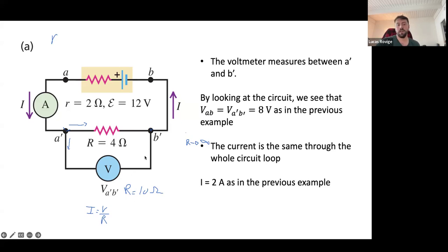And if you have a non-zero resistance there, and you're passing a decent amount of current through your system because you want to power something, then you have a decent amount of current going through your voltmeter, and since it has a resistance, it will dissipate a lot of energy, and so you might even burn your voltmeter because of that.